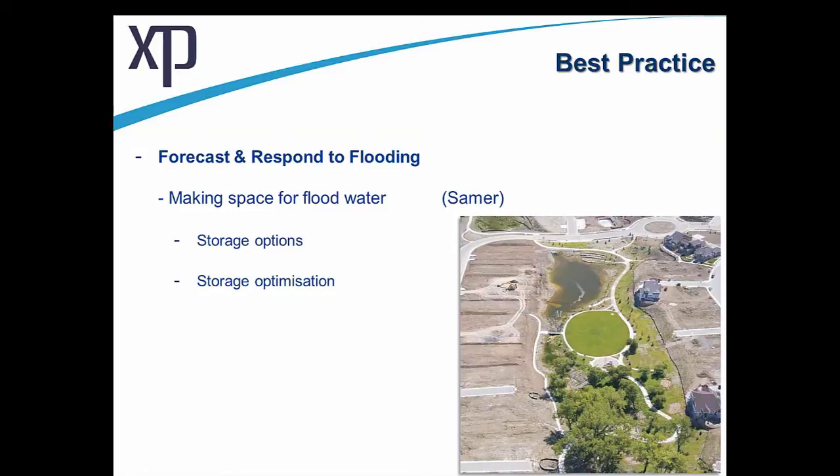So after my brief introduction, Samer is going to explore a variety of options in helping you to mitigate flooding through the creation of ideally additional space, such as floodplain channels, or we can provide storage facilities, and these could be either above the ground or below the ground. As we start entering in storage volumes under the ground, the costs increase exponentially, so it will depend on which is appropriate for your particular situation.